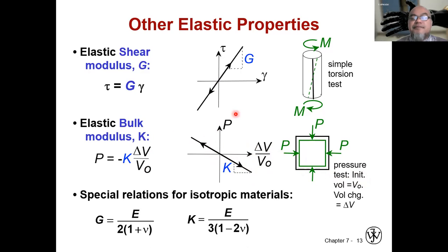For isotropic material, what is isotropic material? Remember, isotropic materials usually, when polycrystalline, have spherical crystalline grains. So it doesn't have any particular preference of orientation towards a certain direction, almost uniformly oriented similarly in all directions. For such material, which we call isotropic, the G, the shear modulus, is related to the Young's modulus with this equation: G equals E divided by 2 times (1 plus nu).